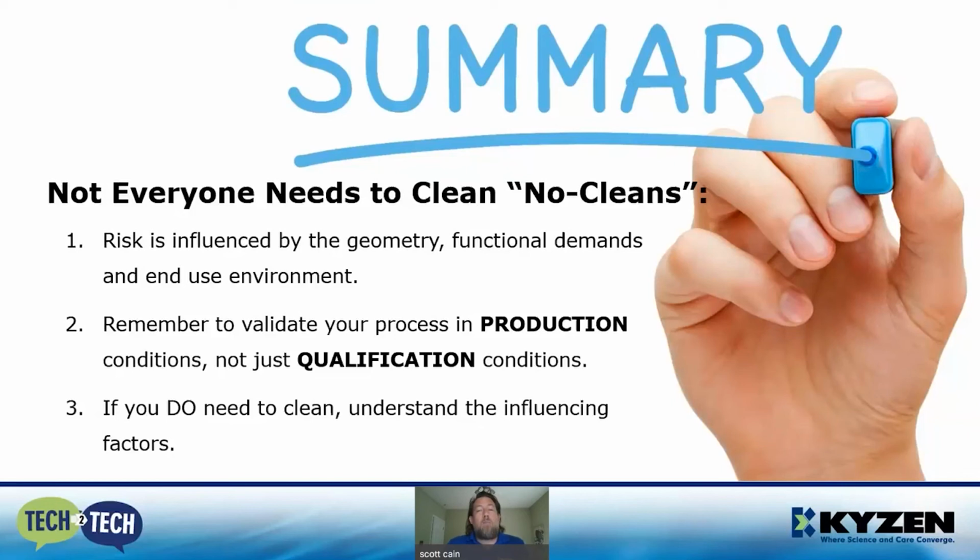That's where you can have more problems cleaning your no cleans, if you're not staying within the standards that you set during the qualification. And if you do need to clean, understand the influencing factors: your time, your temperature, your speed if you're doing an inline, or how long it's going to be in the wash cycle, rinses, your water quality, all these types of things.